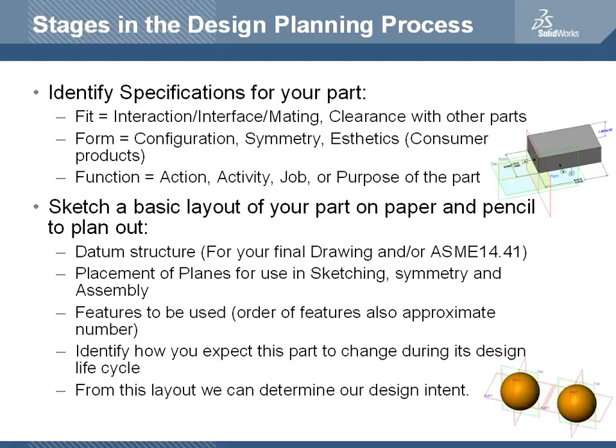One of the things that I like to talk about here for number of features is you want to utilize the number of features to accommodate all the changes that you expect to see, but yet you don't want to go overboard utilizing 5 features for an 1/8 inch fillet when all of those fillets could have been done in one feature. So, you want to use the number of features that are necessary.